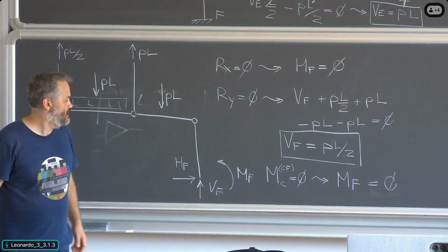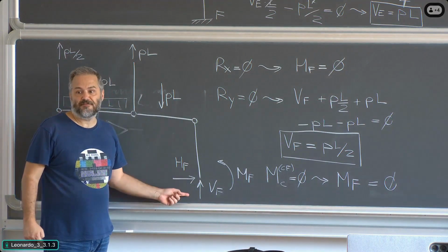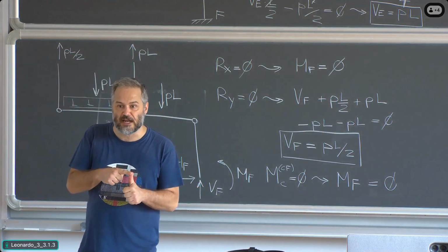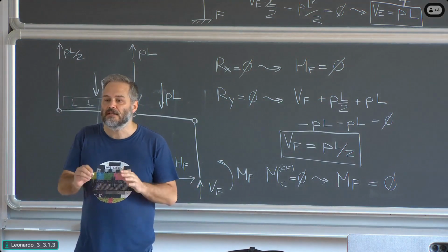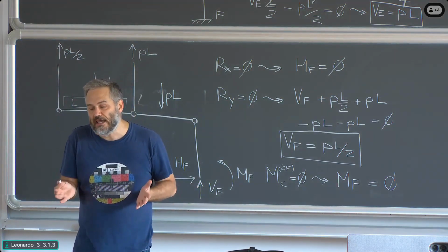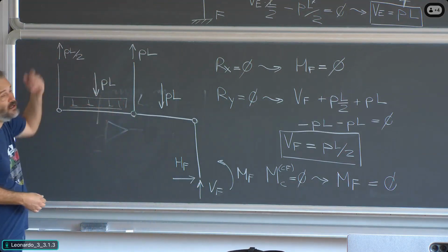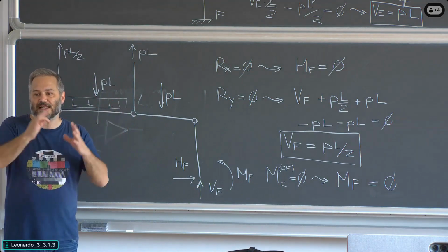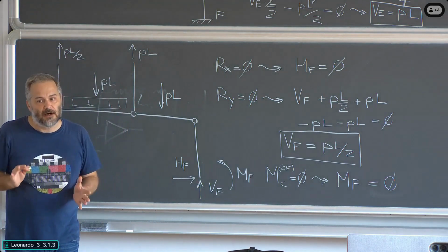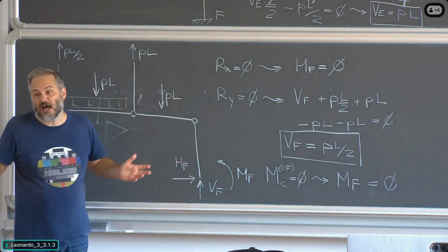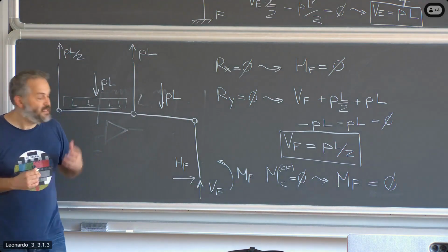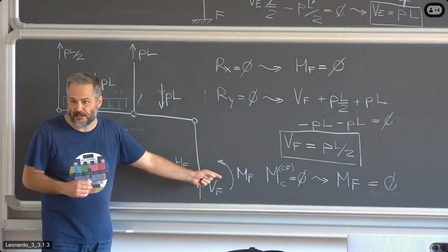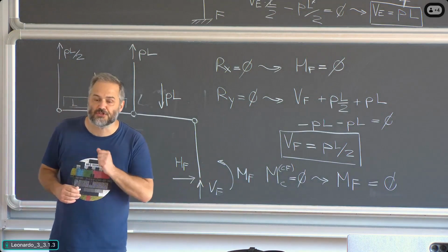So even though at the bottom of column CF we have a restraint which could provide restraint both in the horizontal direction and as regards rotation, in this case the reaction forces are 0. Why? A simple explanation is that if all the loads are vertical and the structure is, like in this case, statically determined with a certain geometry layout, then the reaction forces are vertical only. We don't need to prevent something by means of horizontal force or bending moment. Okay?